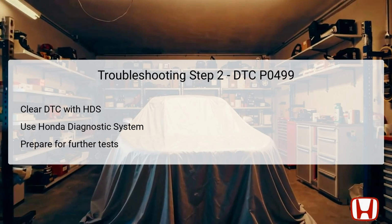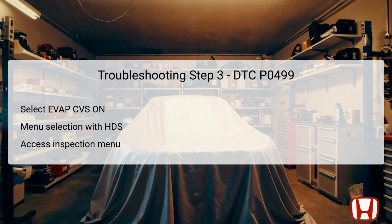The third troubleshooting step involves selecting the EVAP CVS ON option in the inspection menu using the HDS. The abbreviation CVS stands for Canister Vent Shut, which refers directly to the component this diagnostic code impacts.